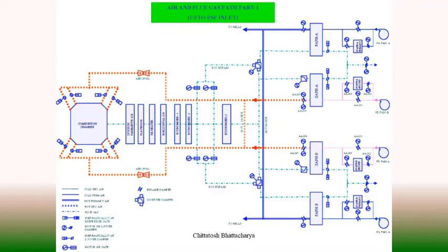Now after the combustion, whatever product is there, it is passing through various heat traps, like heat is absorbed in furnace water walls within the evaporator chamber, then primary and secondary superheaters, then reheaters, then economizers, then air preheaters, and after that it is passed through the ESP and mechanical dust collectors, and then it is evacuated by ID fan and disposed through chimney.